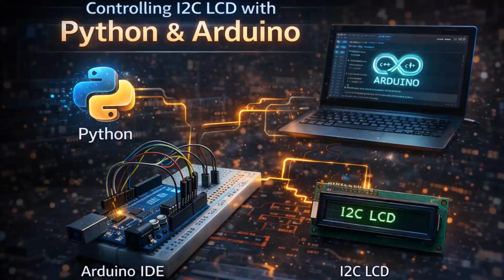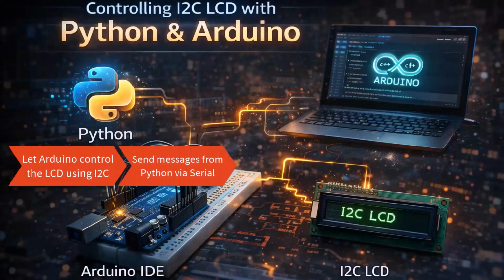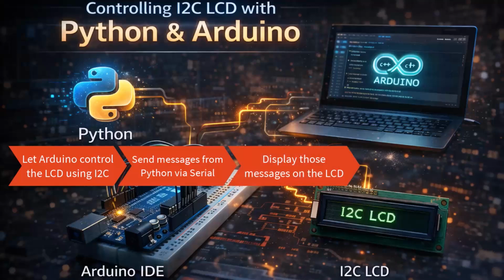So instead of forcing Python to control the LCD directly, we will let Arduino control the LCD using I2C, send messages from Python via serial, and display those messages on the LCD. So this gives us stability, simplicity, and professional design.